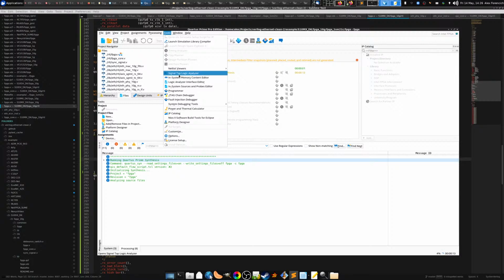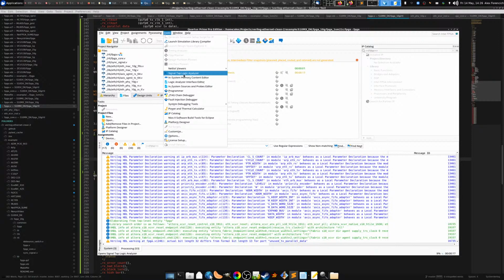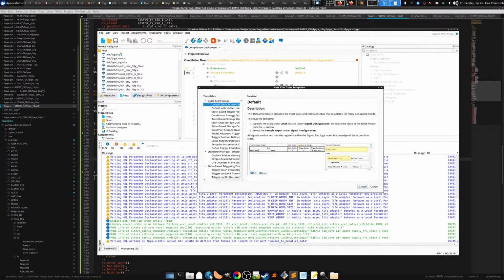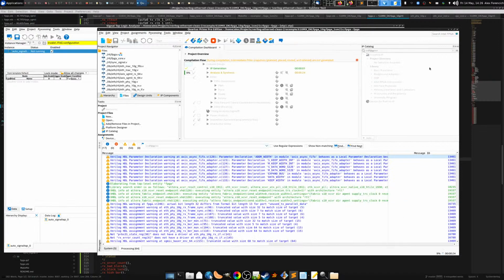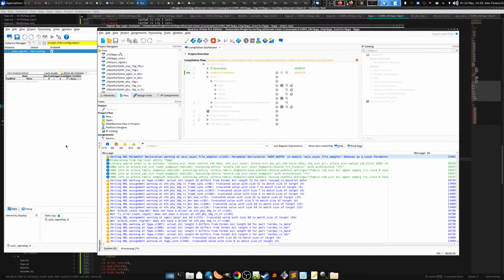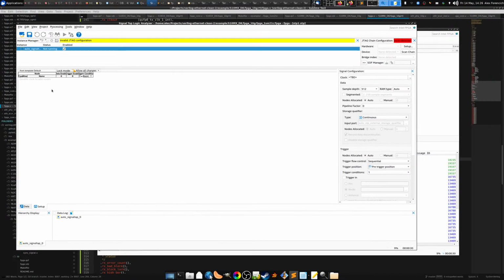So in Quartus, it's, in my opinion, significantly better integrated into the rest of the tools. I can just push the button for the Signal Tap logic analyzer, and I can create a new one. Yeah, okay, that's all right. There's an invalid JTAG configuration. Well, that's fine. I don't have anything programmed yet.